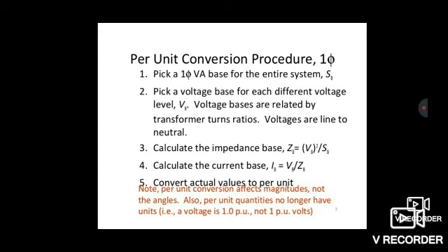We have to note one point: the per unit conversion affects magnitude only, not the angles. Also, per unit quantities no longer have units. That is, a voltage is 1.0 per unit only, not 1.0 per unit volt.